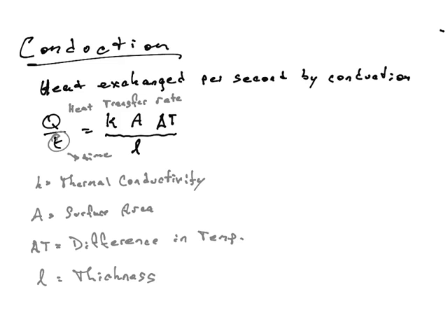If we're looking for how much heat is transferred in a certain period of time, like how much heat would be transferred in 2 minutes, then we would take this equation and solve for Q instead, and it'd be K A delta T over L times little t, where little t now is some time given in the problem. So there's two ways. It's the same equation, obviously. It's just t is on one side or the other, depending on what the question asks us.